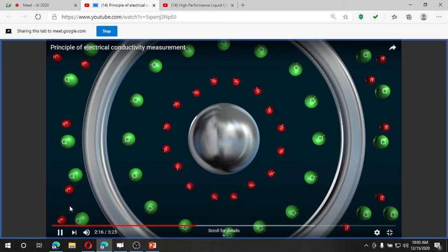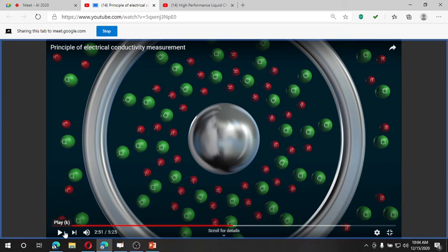If, however, the ion concentration becomes too high, the Coulomb force increases. This electrostatic force leads to a mutual repulsion of the ions, and thus a reduction of the current. The effect is called polarization and occurs with highly concentrated media. For highly concentrated media, you have abundant ions which may cause polarization of the electrode. So when polarization occurs, your current will reduce. To avoid this effect, we can go for the inductive method.